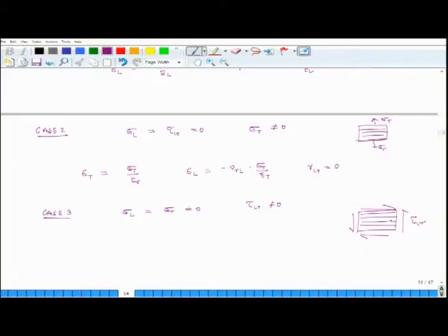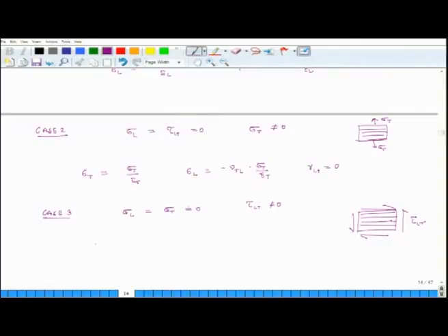If I applied shear stress in the other direction, then it would be negative shear stress. So, this is a positive shear stress, this is our convention, and in this case gamma LT equals tau LT by shear modulus of the material, and the extensional strains in transverse and longitudinal directions, they are both 0 because of special orthotropy.